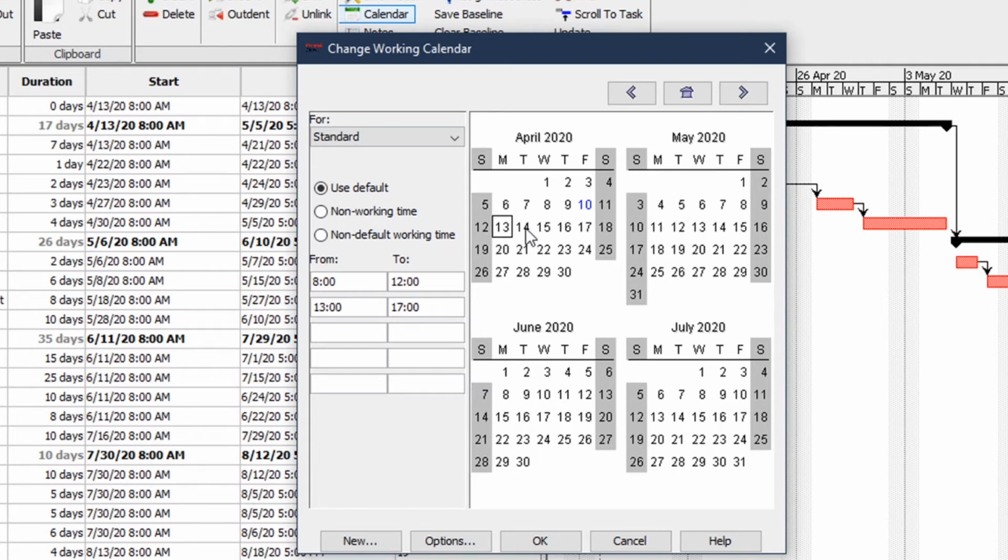To change that, you can select one day. If you need to change only one day, you can change it. For example, you can create a short day, so you just type another value here and click OK. So I will undo that. To work with all days, for example, you need to create a short day each Friday. So you click on F, and you can see all Fridays were selected. And now you define values for all Fridays. For example, you can make them shorter. For example, 15. So this is the value for our new schedule.